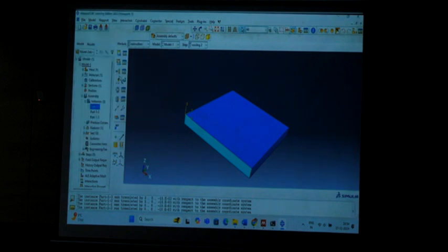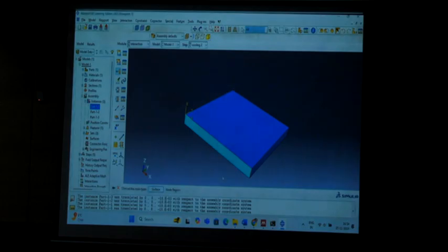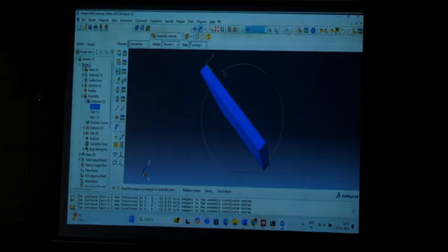So go to dismiss. Here if you can see, create constraint, tie, continue. It will ask you on which region you want to choose the interface between. So this is the top layer, we want the bottom surface of the top layer and the top surface of the bottom layer. In that case, I will choose the option surface. I will just rotate. I will choose this surface, it was highlighted, and then done.